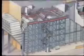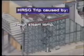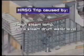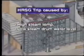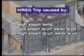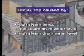So what are the conditions that will cause an HRSG trip? Typically, these will be such hazardous conditions as high steam temperature, which could damage the steam turbine internals; low water level in the steam drum, which could lead to overheating of the tubes in the evaporator section; high water level in the steam drum, which may lead to carryover and consequent damage of the steam turbine internals.